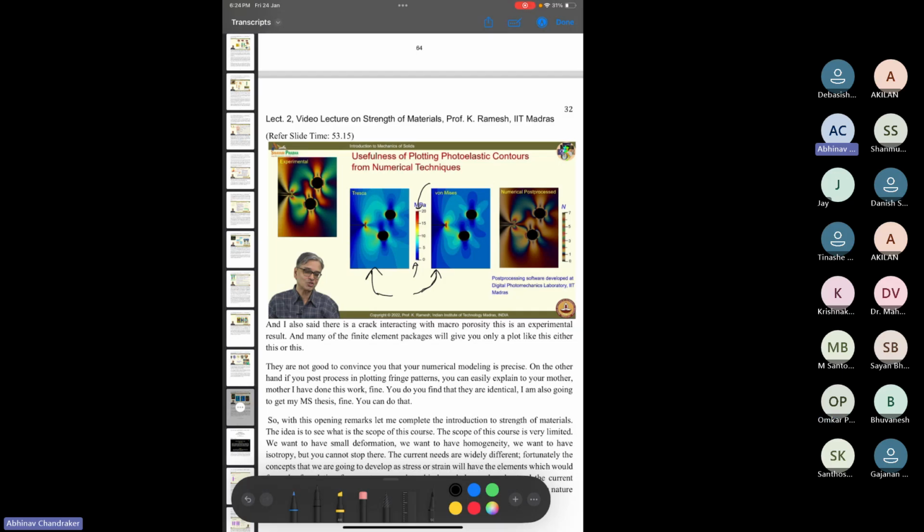These might not exactly be the stress values. This might be in a particular direction, but he has converted this to a more representative stress value, which can be compared to the experimental photoelastic fringes which you see in the photoelastic material. This will give you an average stress value which is being experienced at any particular point in the material, and you can compare this numerical result with the experimental one. Just like you had a gradient from 0 to 20 megapascal for the FEA one, you can also develop a similar scale for understanding what the particular color of the fringe is telling you about the stress value. Here you can see that there is a similar scale.